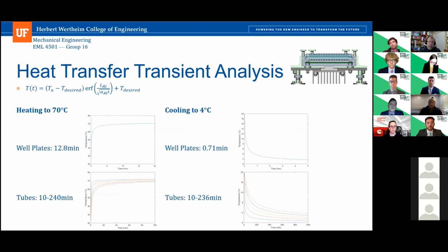Yes, there's a perfectly good explanation for this. The multi-stage Peltier plate that we're using already has a very high temperature differential, and to find one that has an even higher temperature differential, the cross-sectional area that's exposed to the metal gets smaller and smaller, and the heat transfer becomes much less efficient. So this is sort of a limit of the technology.